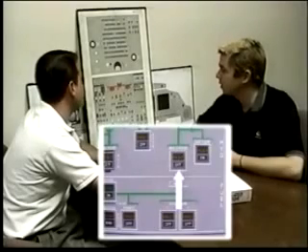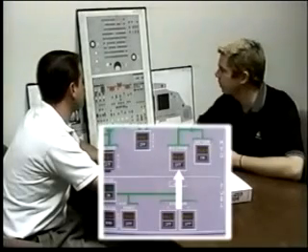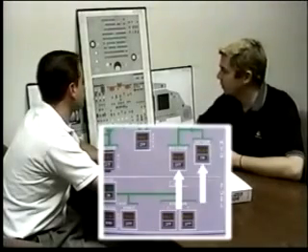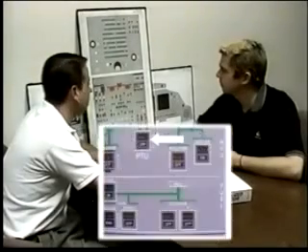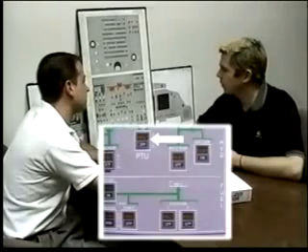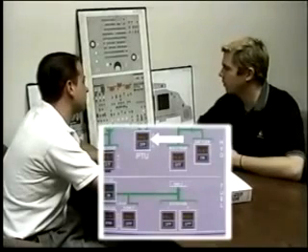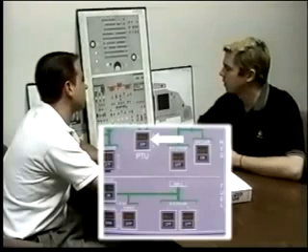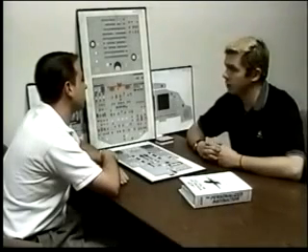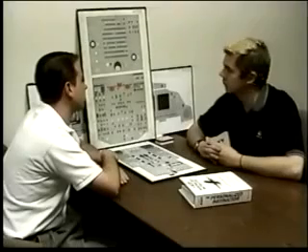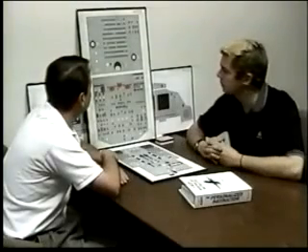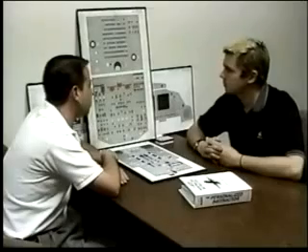How many ways to pressurize the yellow system? There's the engine-driven pump, the number 2 engine-driven pump. There's the electrical pump, and then again the PTU. Can you describe to me this PTU? Yeah, it's a power transfer unit, and it operates between the yellow and the green system. Whenever there's a difference between the yellow or green system of greater than 500 psi, it'll allow the other system to pressurize the low system. Is there any fluid transfer with this?